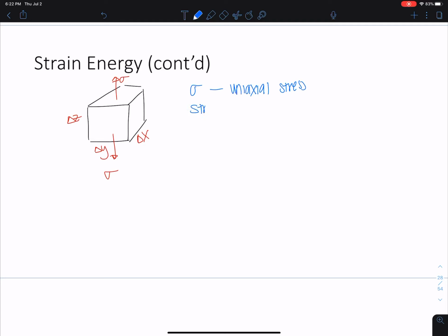So stress, okay? So we have delta F equals sigma delta A. We know this, stress is equal to F over A. And we can say that this is really just sigma times delta X delta Y. That's a cross-sectional area. And this is on the top and bottom faces of the element after the element undergoes some vertical displacement, right, from this load.